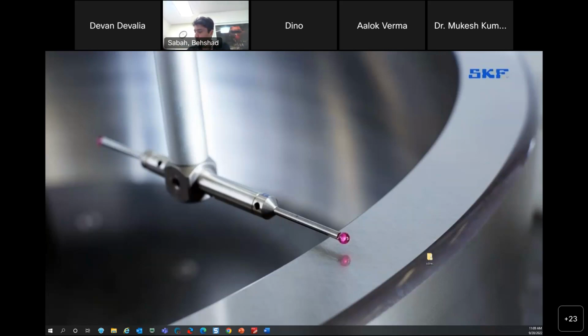You need to be aware of the type of metals in your bearing. If you're using, for example, a polyamide cage, there could be a chemical reaction that will soften and destroy the cage. So we need to be aware of chemistry. The EP weakens and is very aggressive as the temperature goes up.